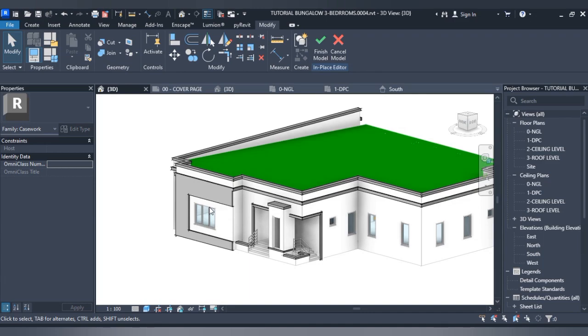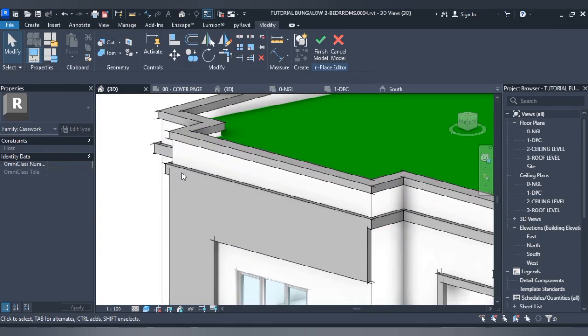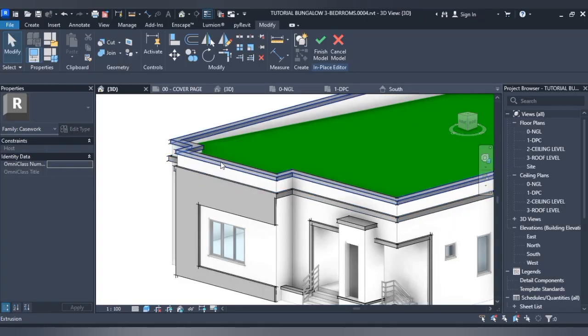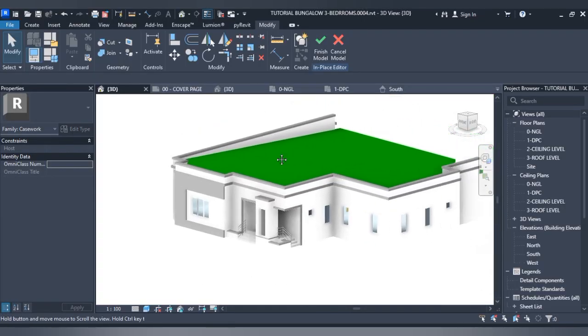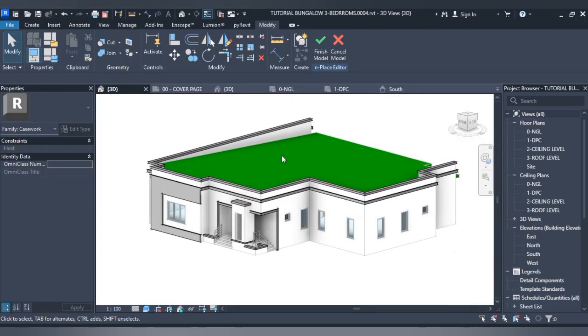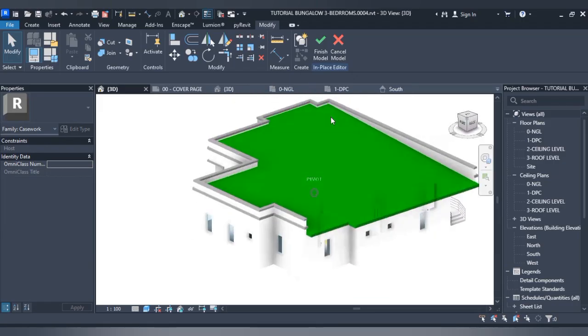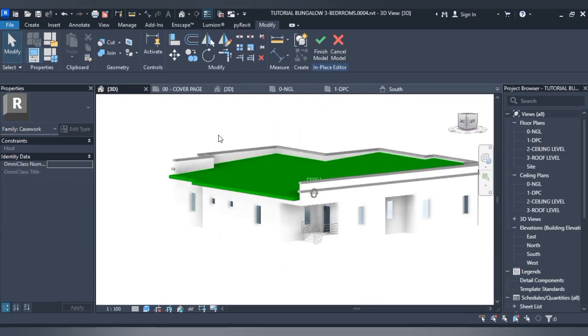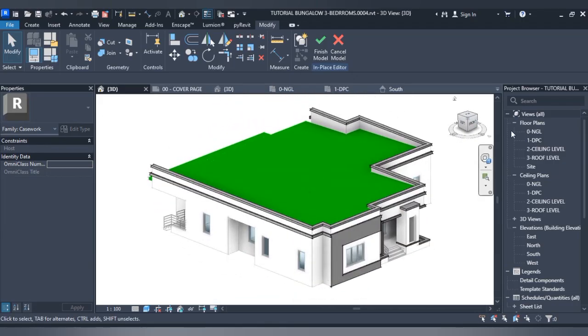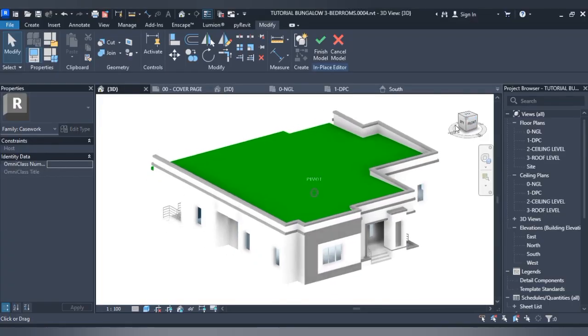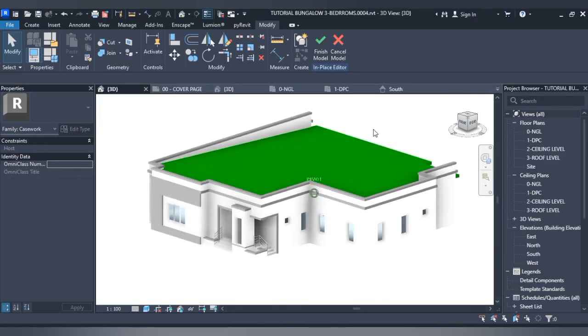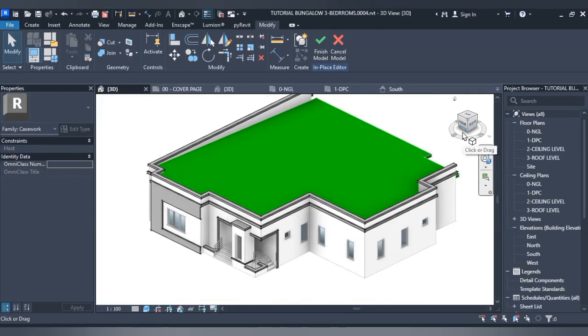Then I will equally show you how to use the paint tool in Revit to paint out some parts to have different textures or different materials from other parts, basically setting up your building. Thank you so much for having stayed with us this long in this tutorial. I hope you have learned a lot on how to use model in place to create Caseworks, the sweep and the extrusion. See you in the next video.